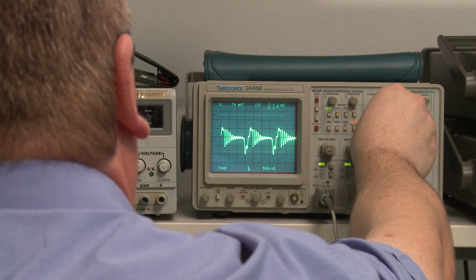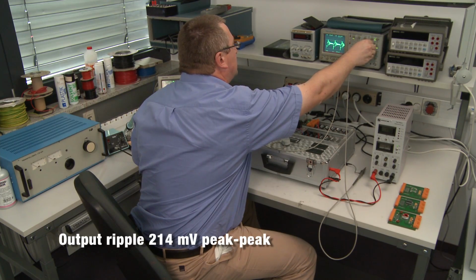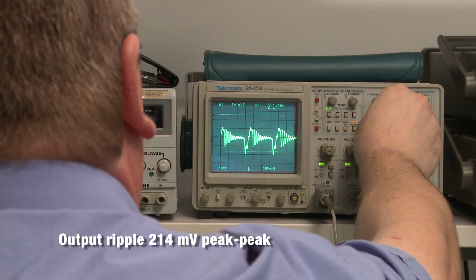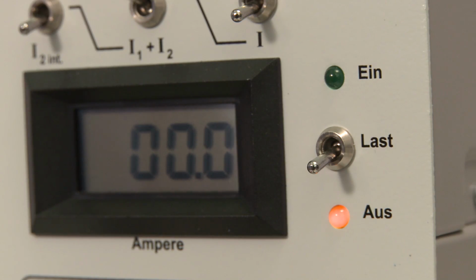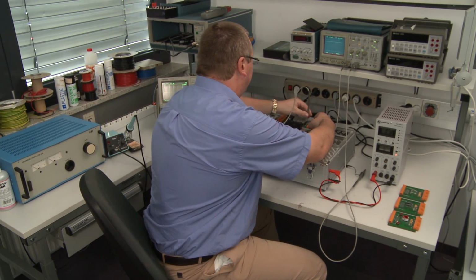And the output ripple is about 214 millivolt peak. In most cases this should be enough, but there are several applications that need a better output ripple. So the next step will be to add an additional output filter.